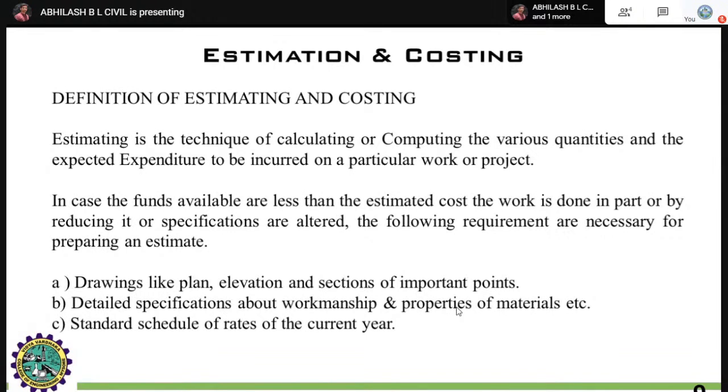For example, you are going to procure steel, right? You will procure that steel in terms of tons, quintals, or kgs. For example, 52 rupees per kg for the steel, multiplied by how much quantity of steel is required for the construction of the overall building, right? Like that, you will calculate and give another column with the overall cost. That will be one column, that is the overall cost.